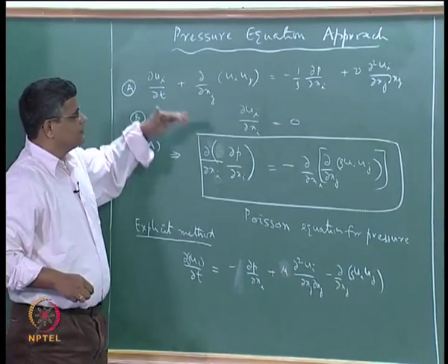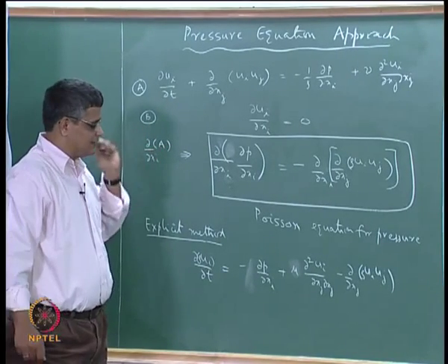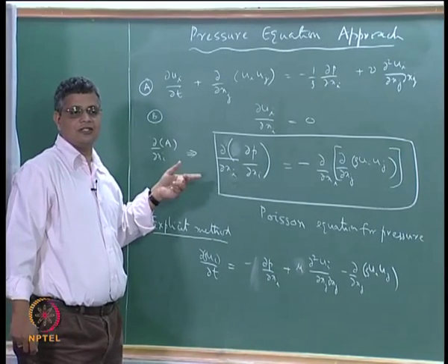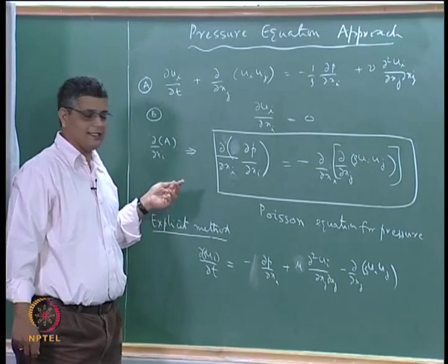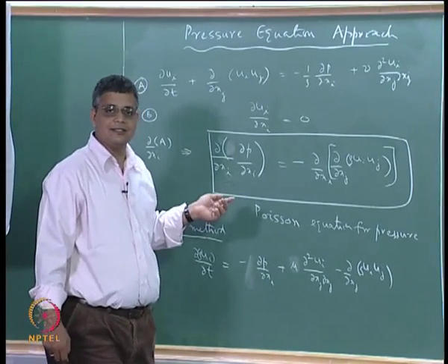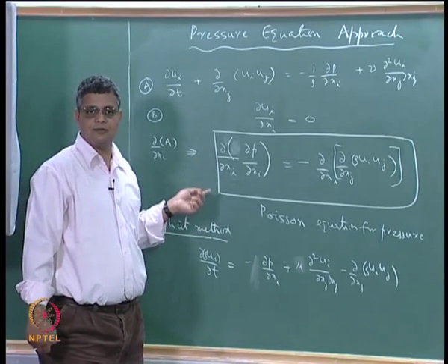And although we are dealing with incompressible flow, we have to remember the incompressibility is something that is coming from the pressure versus velocity relation, for example, as encapsulated in the Bernoulli's equation. We can have other reasons for density variation which is not part of the incompressible flow assumption.